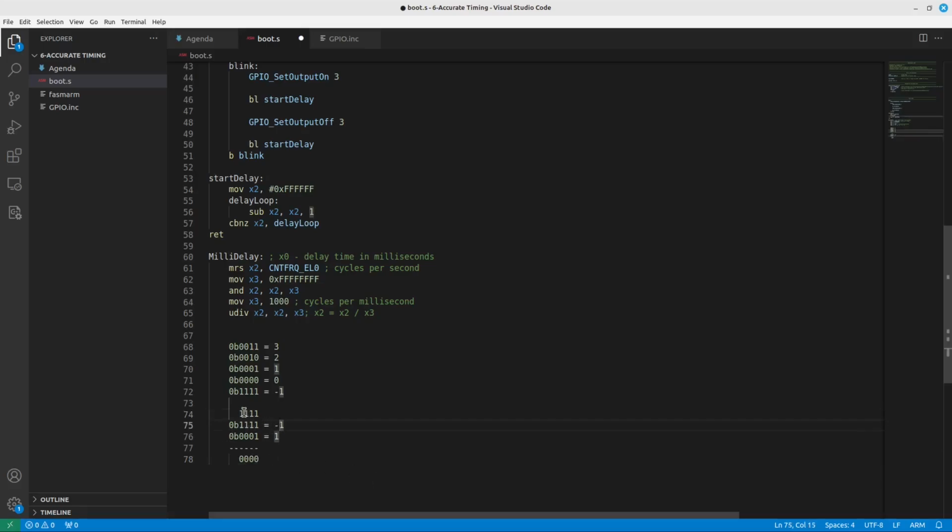All right, we get to the last one. 1 and 1 give us 1, 0. So we put the 0 and we carry a 1, but there's nowhere to put the 1. So we throw it away. Well, actually, we set a flag saying that we have overflowed. But if we look at this result, you can see it's all zeros, which is 0. Which means that this number plus this number actually do equal 0 when you take whatever was in that carrying and you throw it away. So that is how 2's complement works.